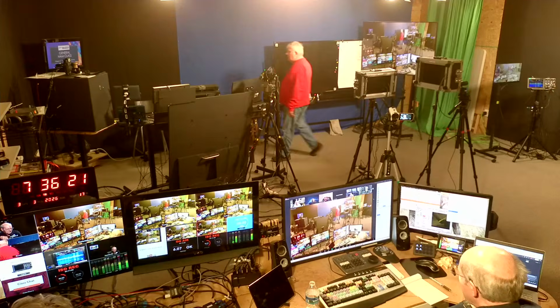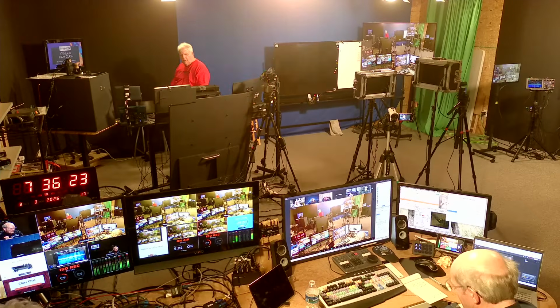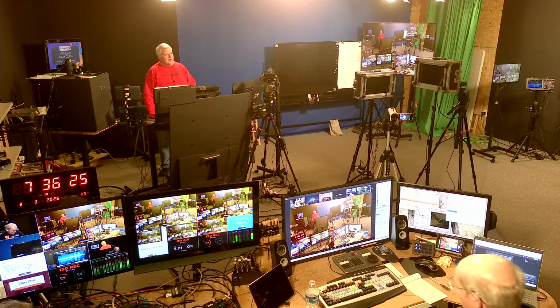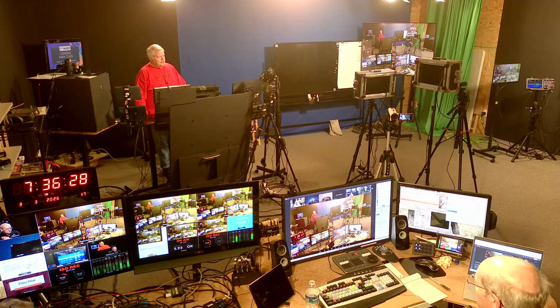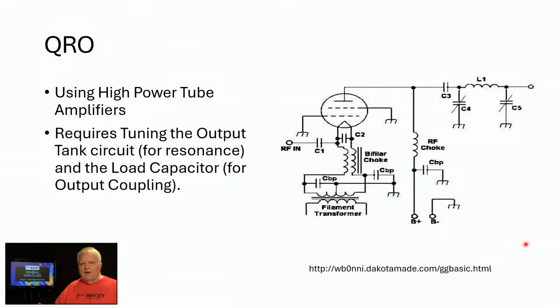Each and every radio in their instruction manual will have a guide as to how to set it up for split operation. Your radio is probably a 100-watt output radio, and most are. But you may want to operate at higher power levels. With the general class license in your frequency range, you can operate at up to 1,500 watts. In order to do that, you're going to have to use a linear amplifier.